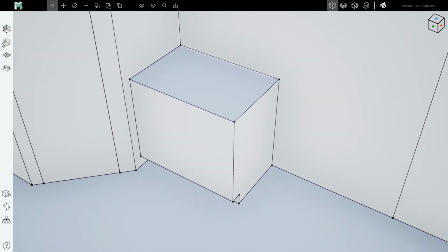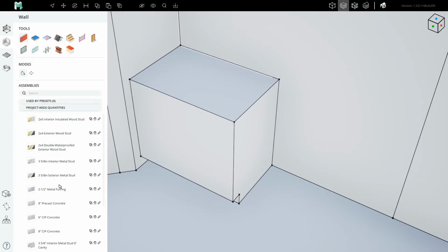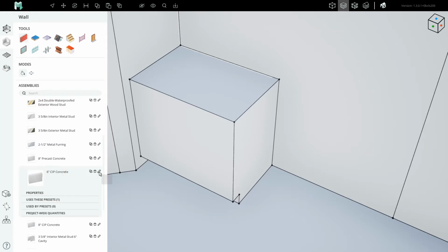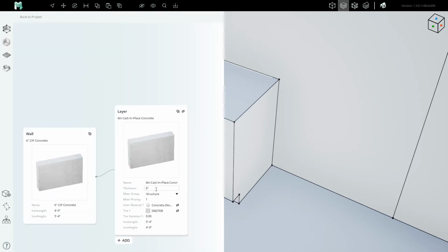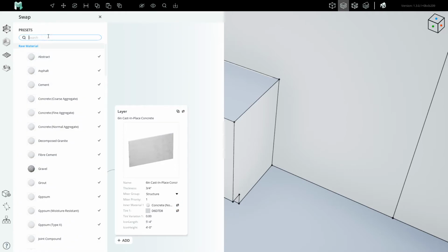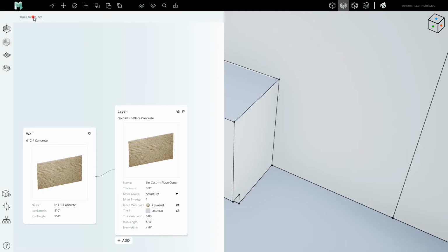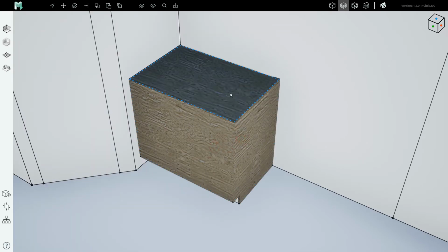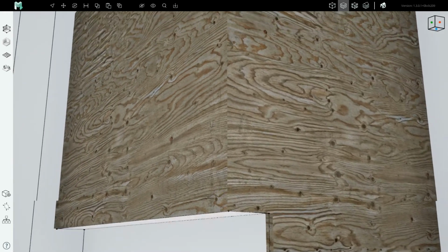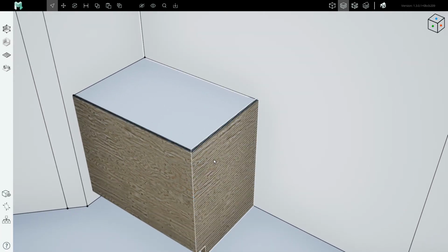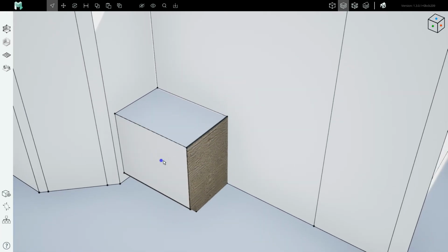Here we will use a wall assembly that we can edit and make very thin. For example, we'll talk about walls again in the future, but if I equip this assembly, if we assume that it's actually going to have a thickness more like 3/4 of an inch and made of something like plywood, I will just very sloppily make a facsimile of a plywood layer here. When I equip this assembly and place it on the sides of the box, we end up with all the construction that we would want to be shown in our DWGs. The front assembly here should not be straight plywood.